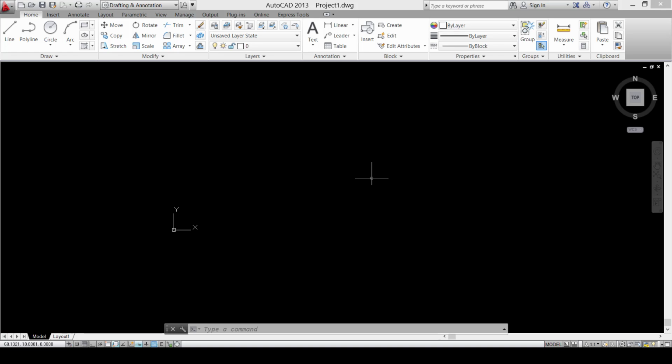Very good. This is the file which we have. I have opened it, but you can see it's a blank file, or we cannot see where the luminaires are. To see the design we have, we can type a command, which is the regenerate command. So we press R, E, G, and then select the second option, which is the regenerate option. This is to regenerate or to locate the design we have. Then I press Enter. That's it. Now I can zoom out a little bit.